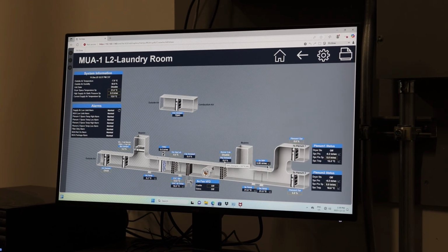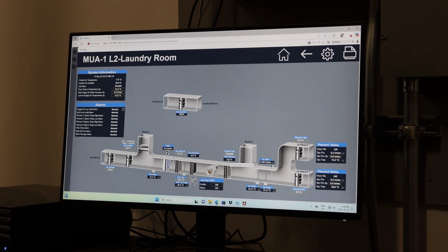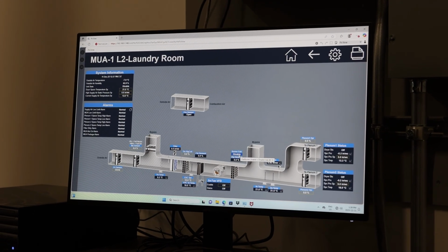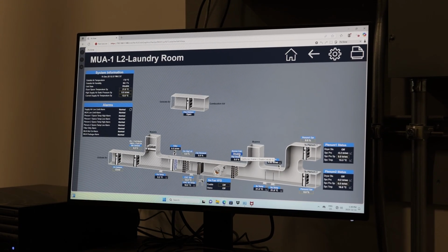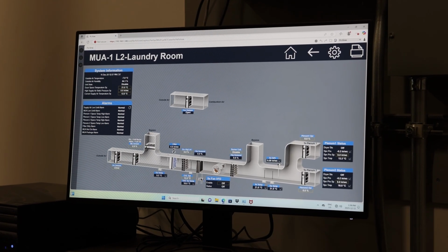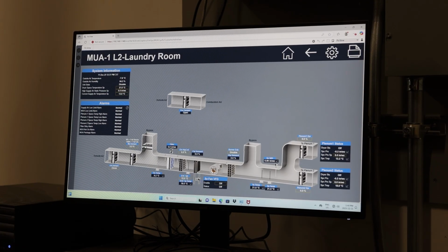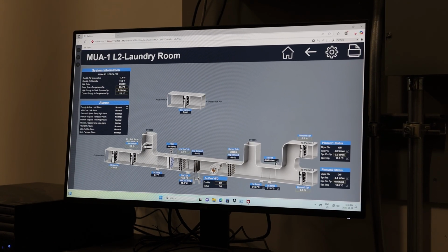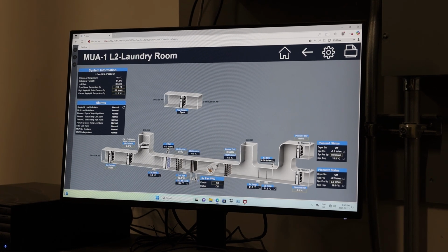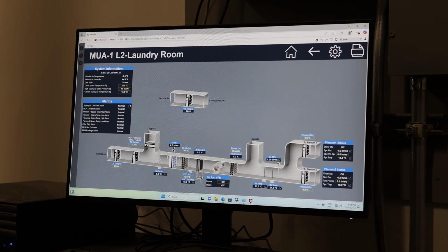There's no need for that. Just the electric heater is enough. But in extreme cold weather, when the outside temperature is below -20, we will enable this. It just provides additional heat in case this is not capable of that much heat. And those two, the cooling valve and the gas heating, work based on the set point. So it's a package control. It automatically adjusts to maintain supply temperature at set point.